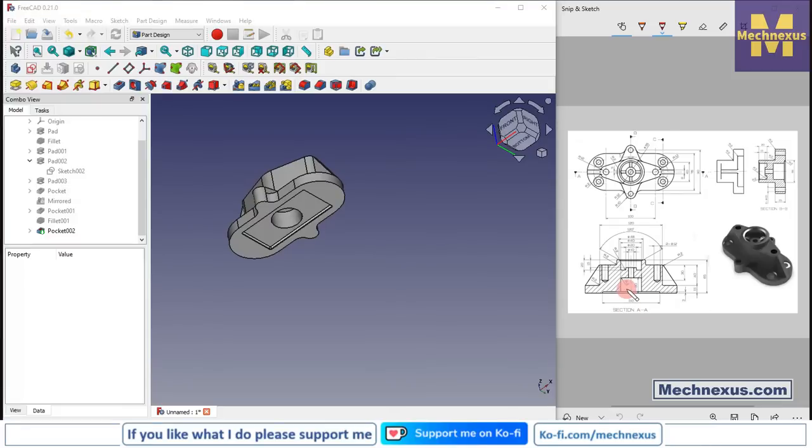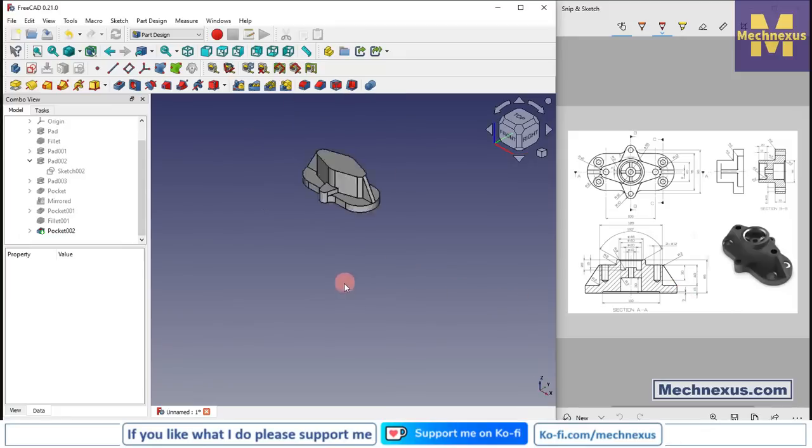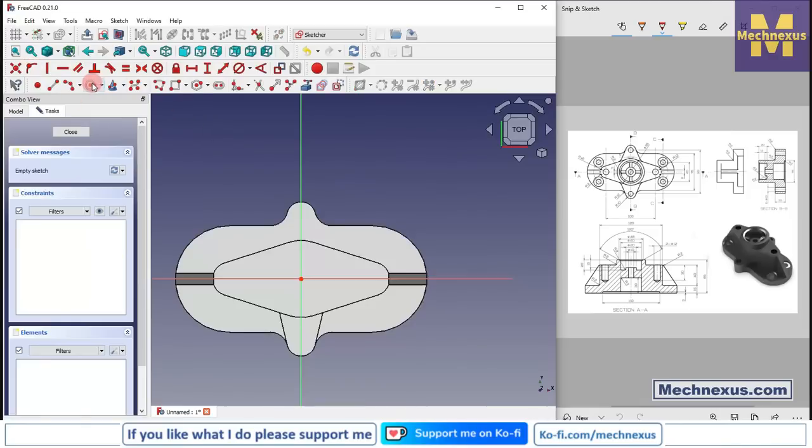And now here is a cut of diameter 20 and 40. So we will place our view to the isometric, and select this top face, and click on the sketch, select the circle, create two circles.